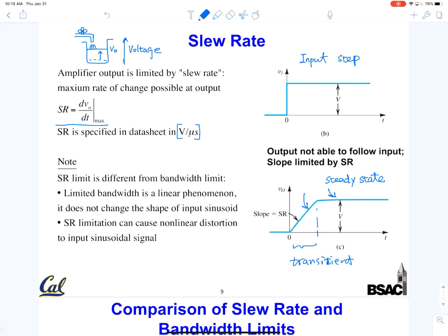There are circuit tricks, certain circuit topologies, that are more amenable to outputting the current very quickly. So these circuit designers labor through their design to produce a higher slew rate. If we are simply users of ICs, well, you just pick them.